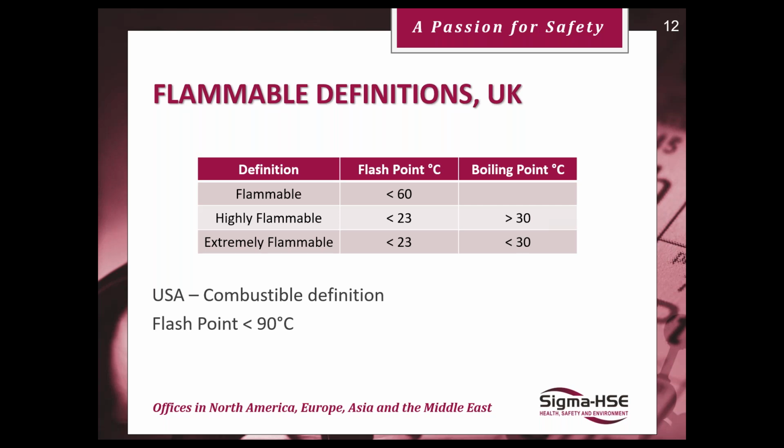And we tend to designate under the various regulations out there, not just flammable, but between flammable, highly flammable, and extremely flammable liquids. Essentially, as we go down the rows in that table, the materials are becoming more volatile, giving off more vapours, hence mixing with the air at lower temperatures and becoming a lot more capable of bursting into flame.